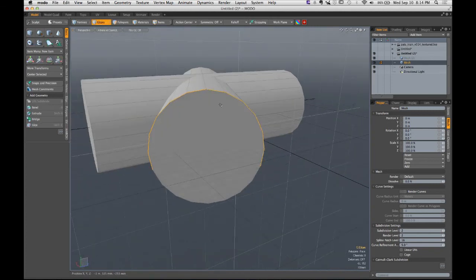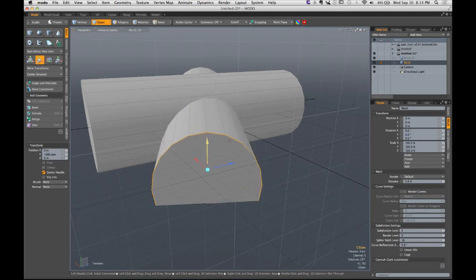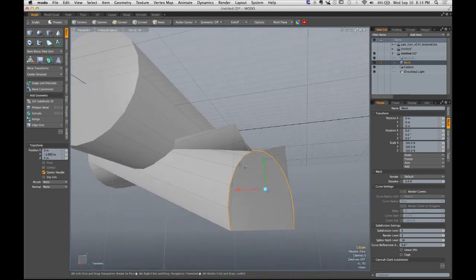Okay, and I did something like that. That's bad. We've crossed the edges. This is very, very bad form. It's bad modeling. It creates massive issues for us on the render side, and it ultimately creates a mesh that's uneditable. Okay? You've got to look at your mesh. You've got to look at your geometry. Be aware of how you're editing your shape, and be good stewards of your project file.